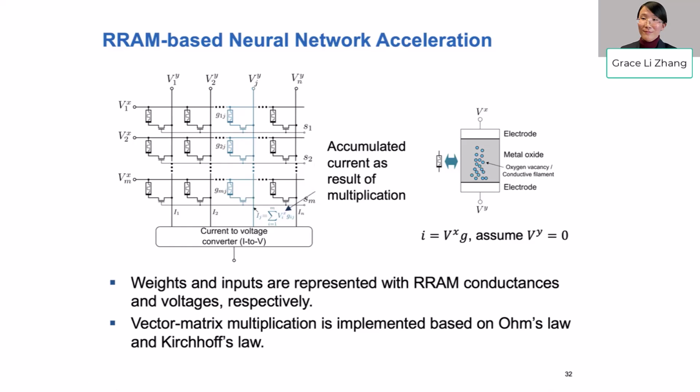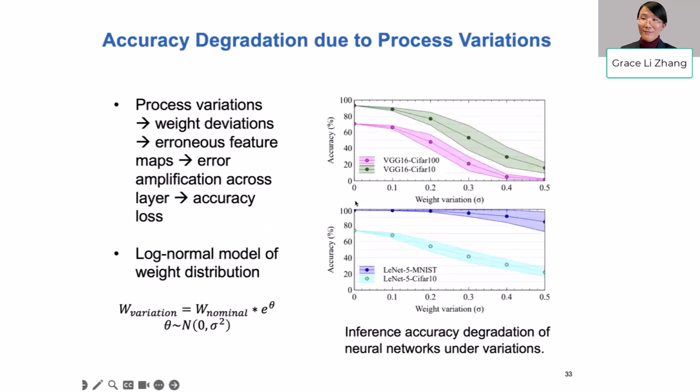On the next slide where you cite these error rates, a weight variation of 0.1, which I interpret as 10%, seems to be large, but is that a typical value, or is a typical value more like on the right of this diagram, like 50%? When we read papers, different manufacturing technologies have different variations. So we simulated from 0 to 0.5, that is the worst case. Usually different manufacturing technologies fall within this range, so we cannot determine that it is definitely such a value, as it depends on the manufacturing technology.